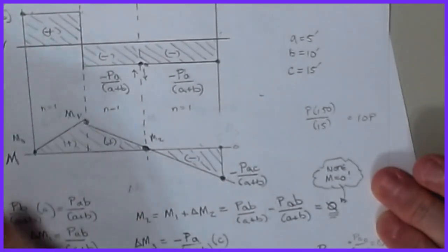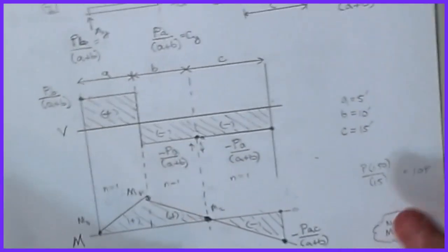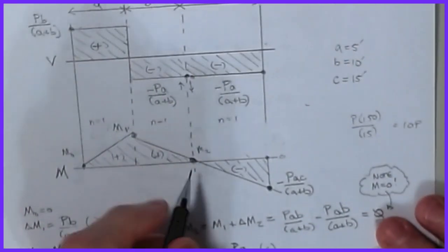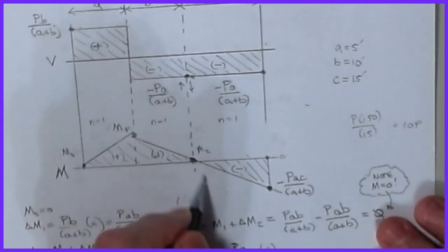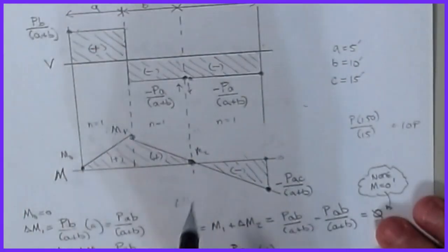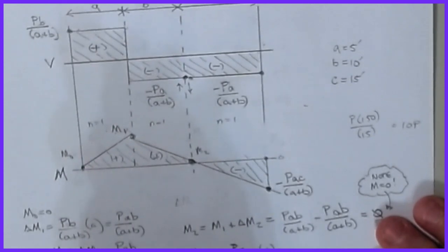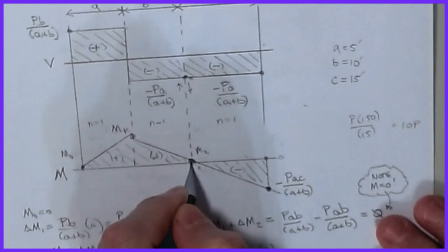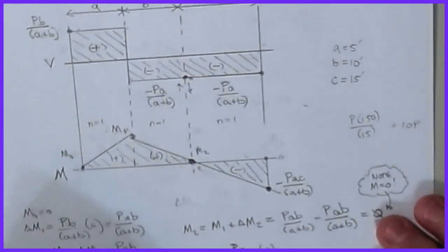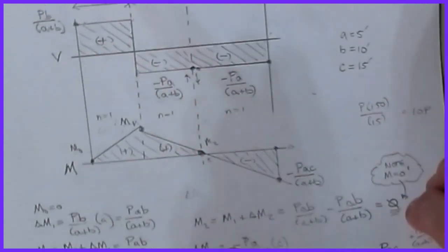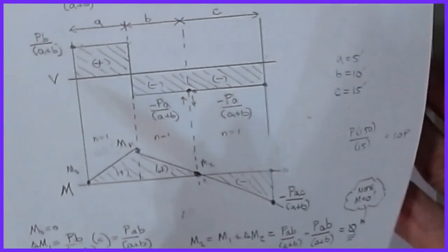All right, so that's what we can look at with these hinge problems. These more complex sections are interesting, but this is the trick: if you recognize that the hinge is a 0 value, then you're in business. I could have almost gone in right off the bat and plugged it in. So if you have a beam with multiple hinges, that's your check. If you don't come in at 0 on that hinge, you know you've got a problem in your calculations. So that's how we handle hinges on our beams.